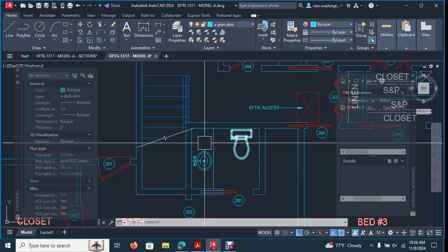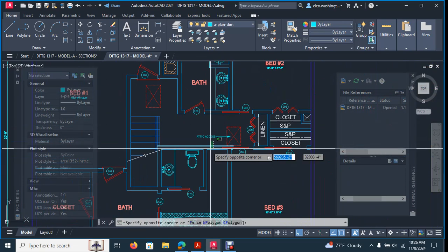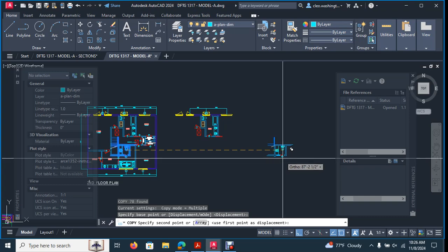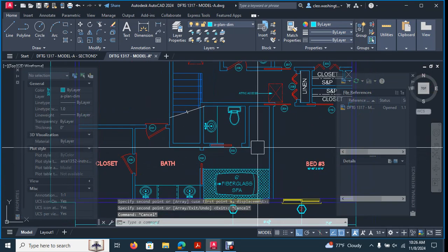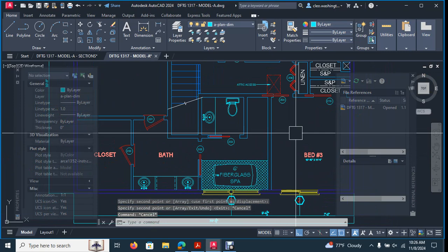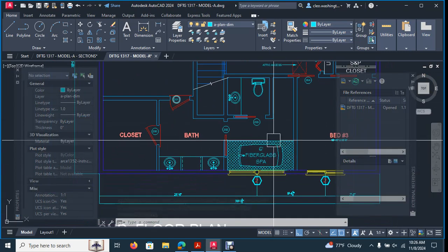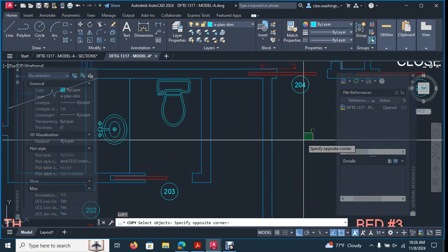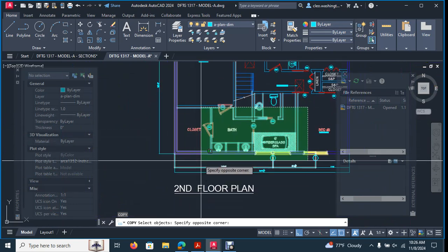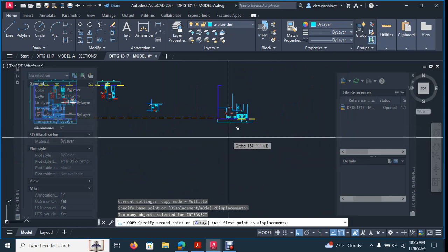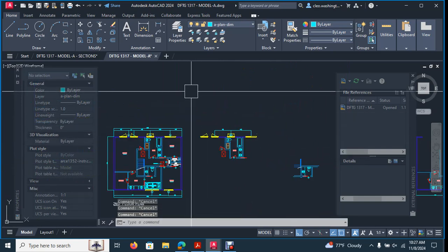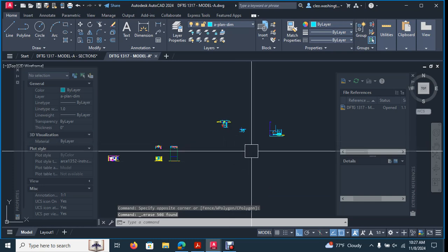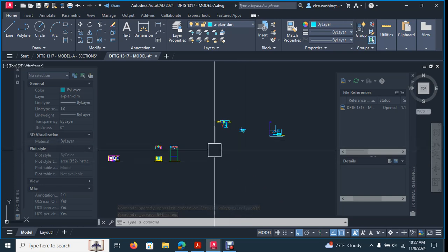We won't elevate this little, well, we'll do them all because what's happening is we're putting together a set of construction documents. So we're going to have to elevate everything, right? So we need that. We also need to have some interior elevations here, especially in this guy. This is a big, huge bathroom. So let's copy this one. And I'll go ahead and get them oriented and set up so you guys can actually take off with the drawing. So you have 1, 2, 3, 4. You have 5 interior elevations.